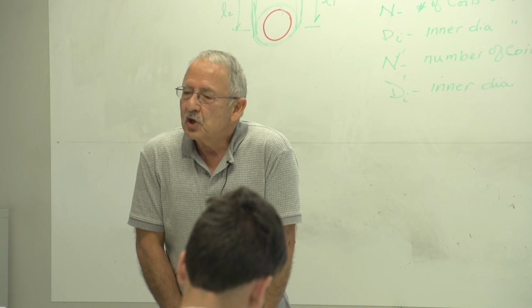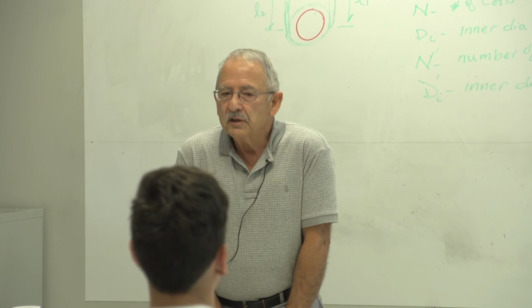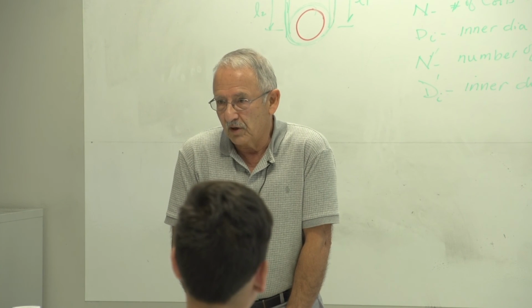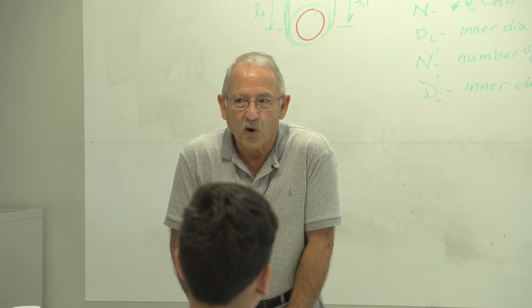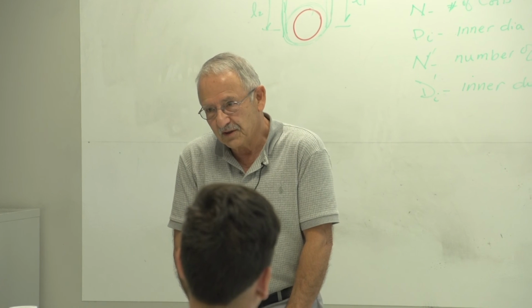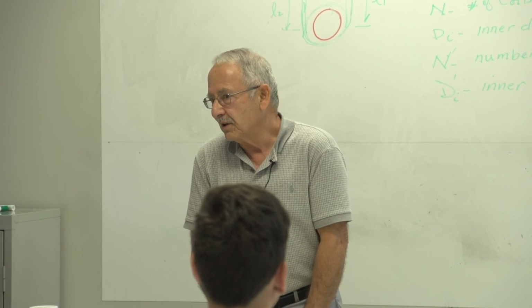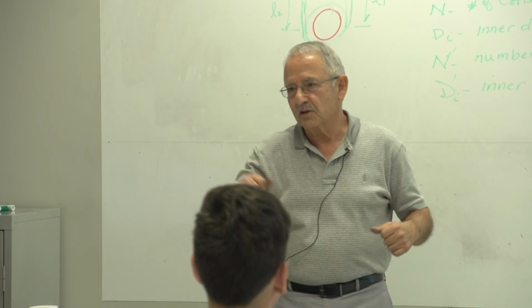It depends on the type of material you have. For high strength materials, the yield and tensile strength are closer to one another. That's why I'm saying 0.6 is low, because we usually use high strength materials for springs. For low strength material, the yield strength is farther apart from the tensile strength.